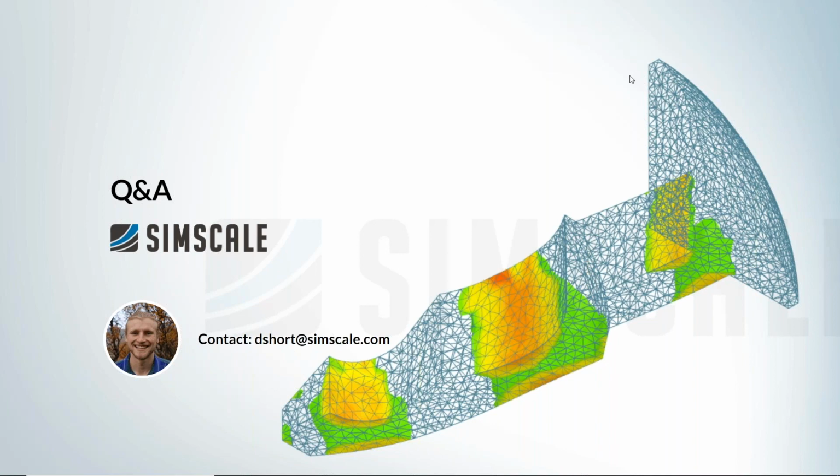Of course. Okay, so with the first one, frictional contacts, that's going to be part of the nonlinear contact definition, and that can be brought into a simulation just like this. You can simply add friction onto the nonlinear contact with a Coulomb coefficient of friction. That's going to be a static coefficient of friction, and you add that in at the contact itself. But you've got to bear in mind that's an additional layer of complexity. It's going to be harder to converge, potentially longer runtime, and in the majority of cases, friction doesn't play a massive role in a lot of these types of analyses. But we have it there, and you're able to then test that out.